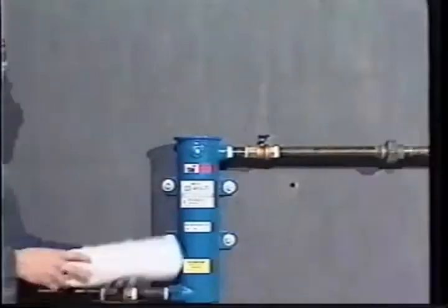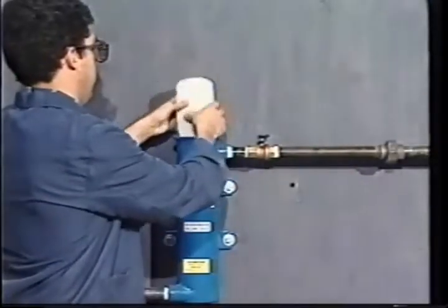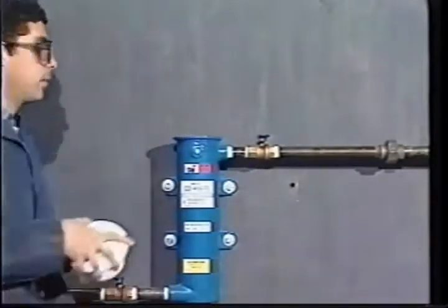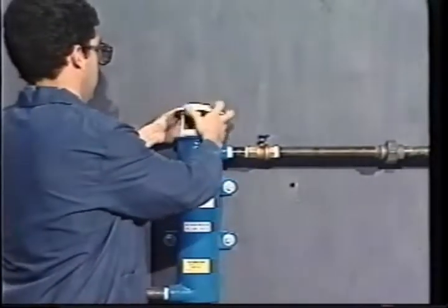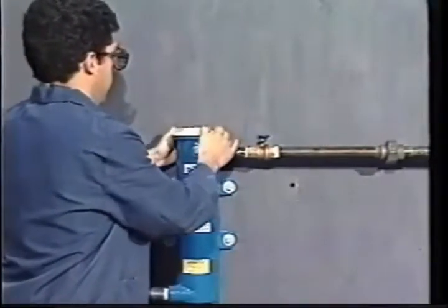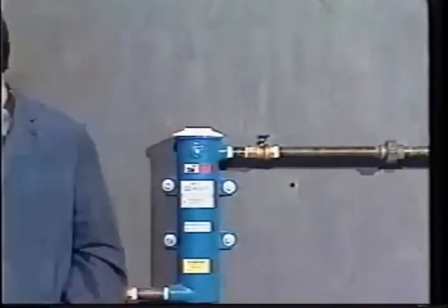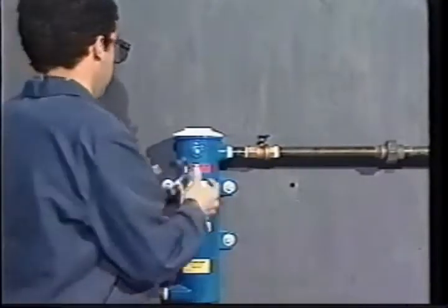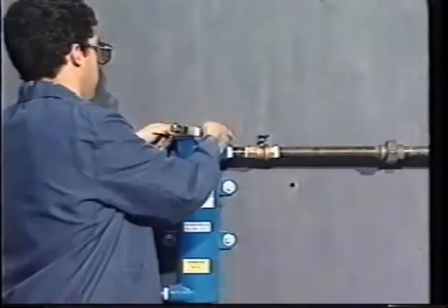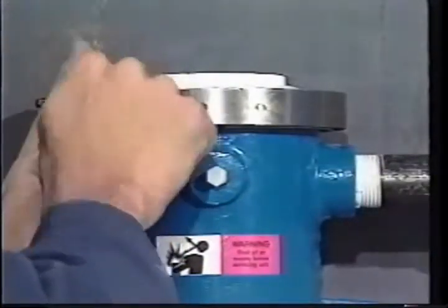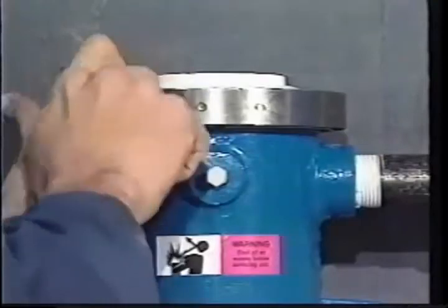The form-fitted desiccant bag fits into a cast aluminum housing, which is finished with a polyurethane powder coating inside and out. This results in a smooth interior, allowing for easy assembly and installation on the bag. Filter discs attached to the cover fit snugly on the smooth interior sidewalls and seal the unit for final filtration. A V-clamp, equipped with disengagement knobs, effectively seals the unit's top cover.